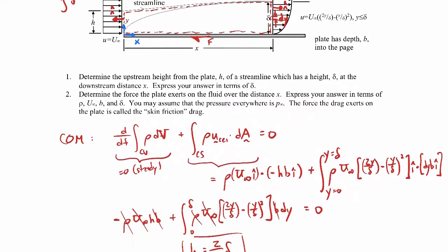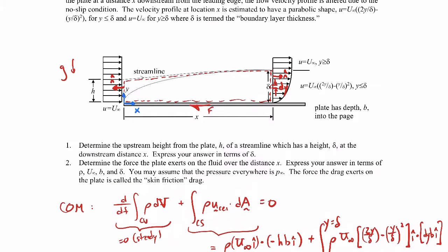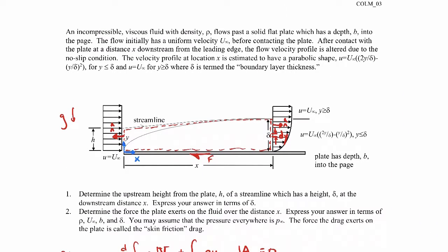Now for surface forces, there we do have something. So let's go back up to the picture. The surface forces that we would have might include pressure and viscous forces and resultant forces, that sort of thing. Well, I don't think we're told anything about what the pressure is in this profile. We're going to assume that the pressure everywhere is uniform, that pressure everywhere is atmospheric pressure.